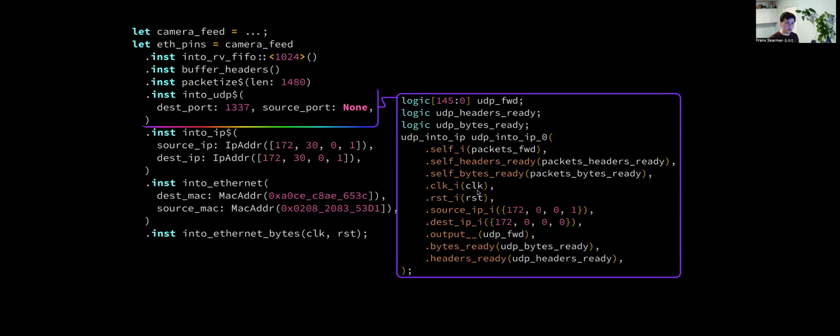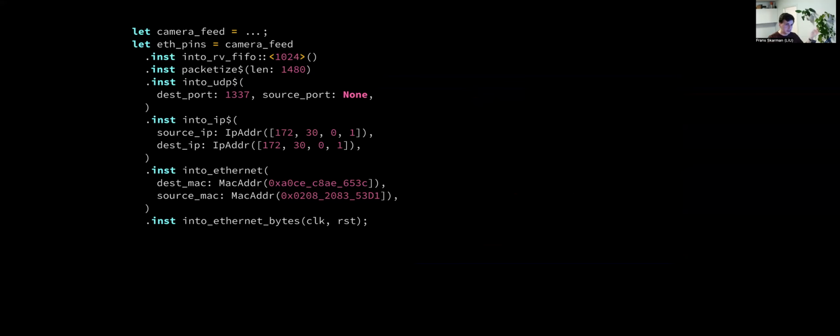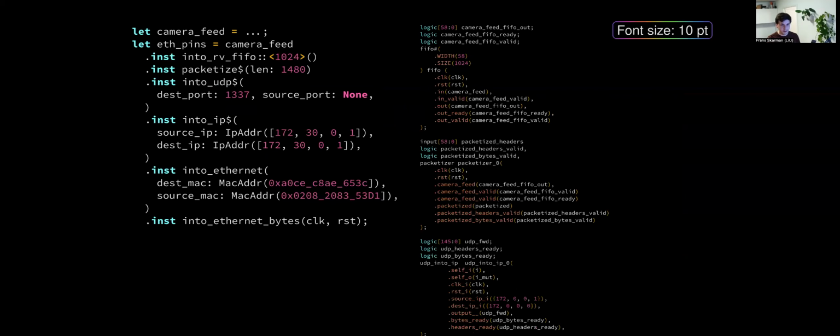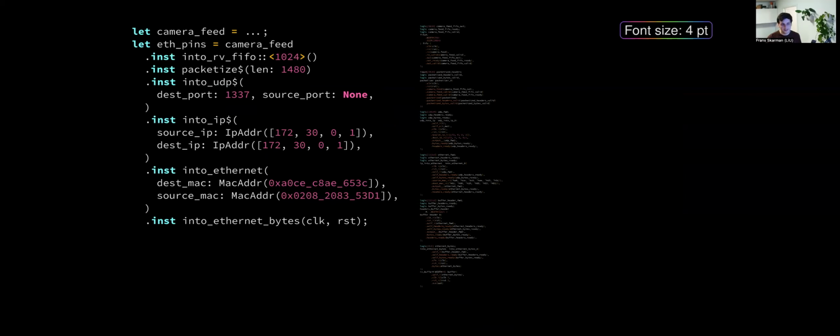So there's significantly less code, and you don't really sacrifice any control, I would say. And if you did sacrifice control, Spade is an RTL level language, so you could replace these method instantiations with a lower level description if you need to. So what that essentially means is the corresponding Verilog is really, really, really long and doesn't say anything. It's just pointless in my opinion.